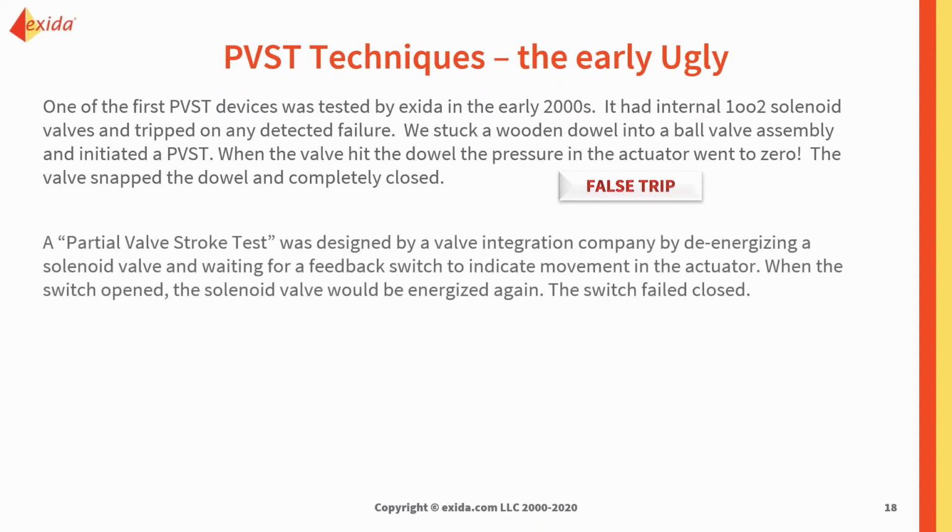Now, we saw another PVST concept that was designed by a valve integration company where they used a logic solver, I suppose to save money, and they used the logic solver to de-energize the solenoid valve while using a position feedback switch to monitor the valve's movement. When the valve moved, they would re-energize the SOV. It seemed like a good idea. Seemed like it would work. Well, in our test, the switch failed closed. The PLC kept the SOV de-energized, vented the actuator completely, and again, we had a false trip.